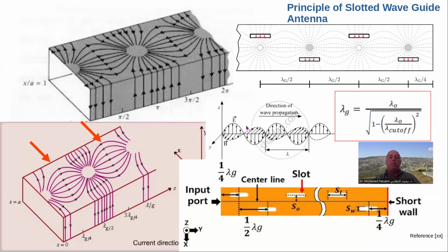If you look at the E field diagram and the magnetic field along the Z-axis, the direction of wave propagation, you can see that the E field is all sinusoidal. So it's always going to be the same dimension, assuming it's a lossless propagation. And then you can see that it toggles between 180 degrees. So within a full wavelength, you will see the E field actually make a full pattern.